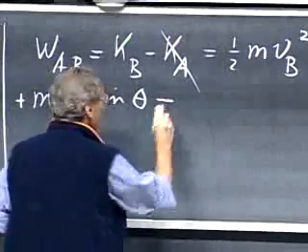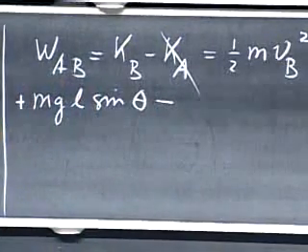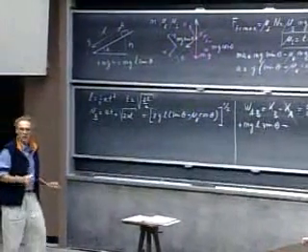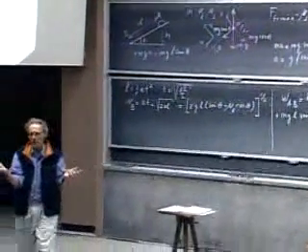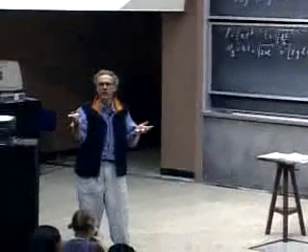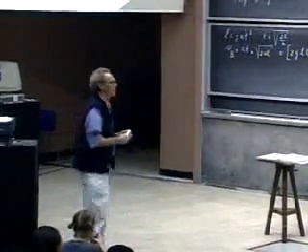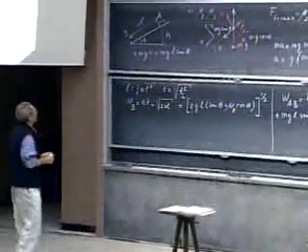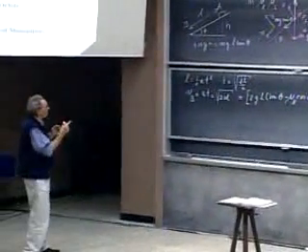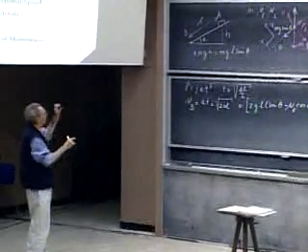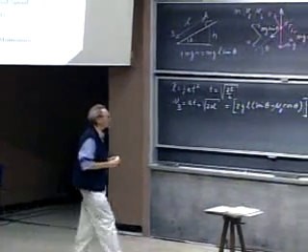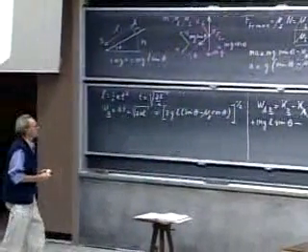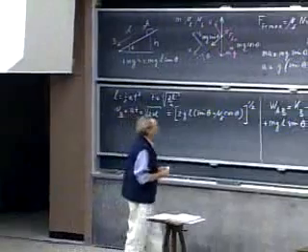And now we get a negative contribution by friction, because the frictional force is uphill, but the motion is downhill. They're 180 degrees opposite, so I don't have to worry about the dot product, because the cosine of the angle is -1. And so I can simply take the frictional force and multiply it by that distance L, but I have to take the minus sign, because the cosine of that angle equals -1.